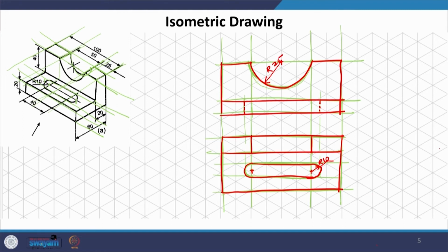You can derive the side elevation again through these two drawings, or you could draw them afresh, but the reference lines, the ones which are going to extend, will have to be the same. You cannot and you should not deviate from these ones. The reference lines must remain the same.